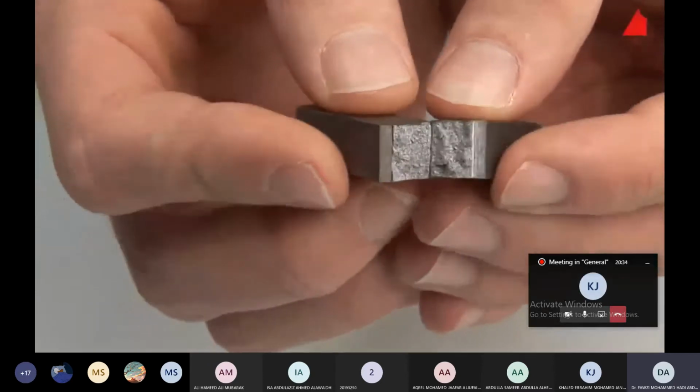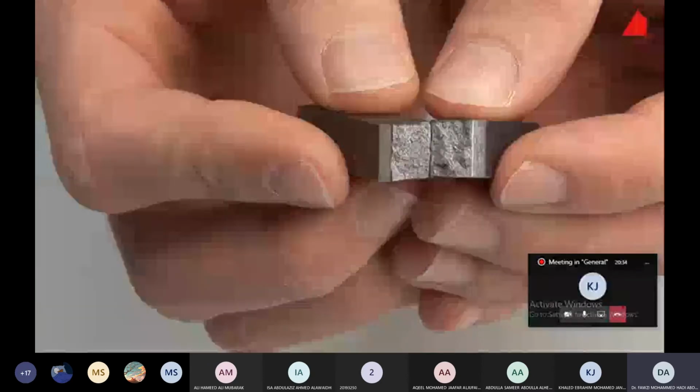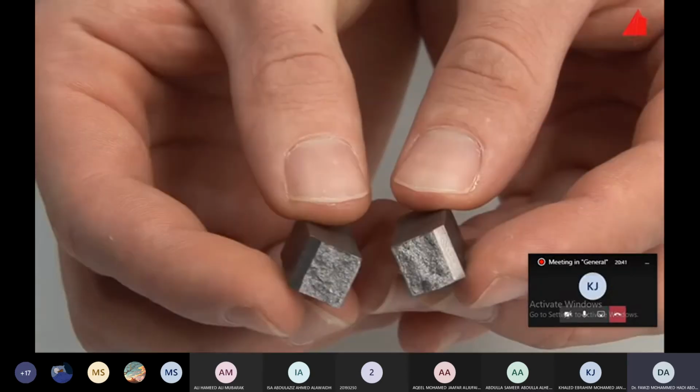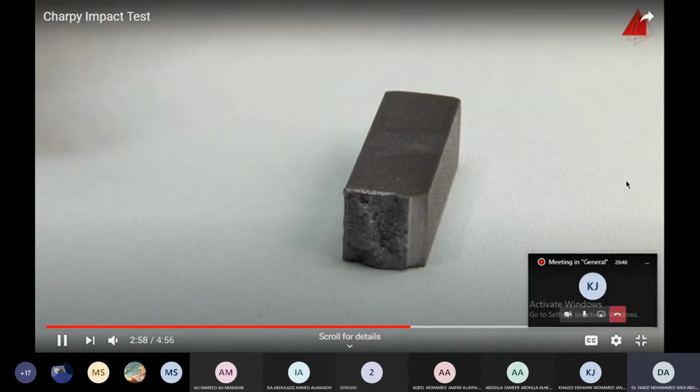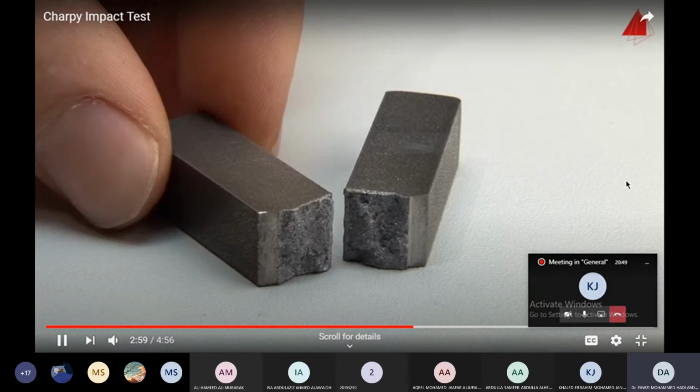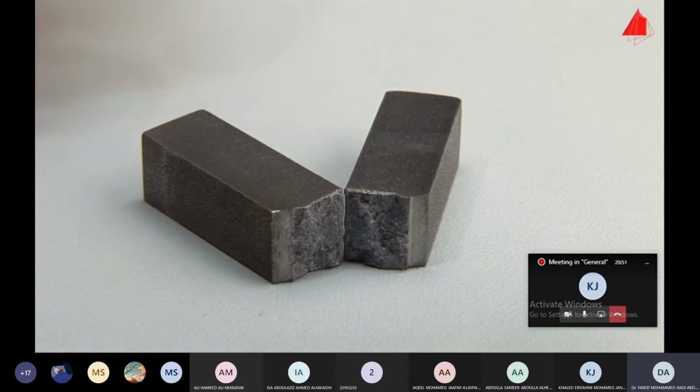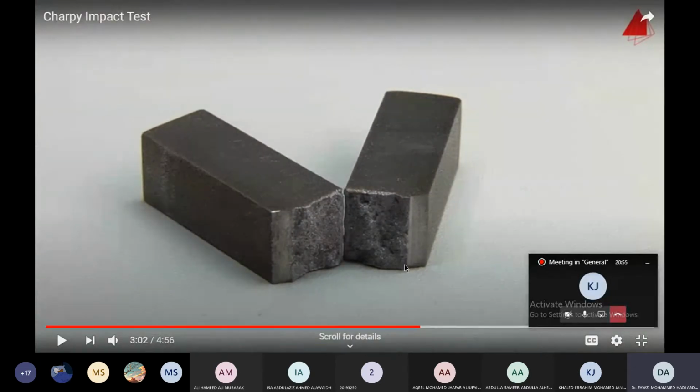The first specimen only shows very little plastic deformation. A mostly flat, slightly glittering fracture surface has been formed. This is another important indication that this kind of steel is only able to absorb small amounts of notch impact energy. It shows mainly brittle behavior due to the strain aging effect. Now, you can see when we strain age, when we cold work any specimen and age it as well at the same time, it causes the material to embrittle. We don't say it's very brittle.